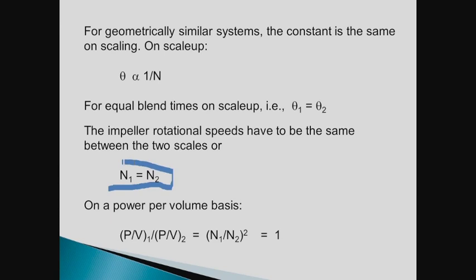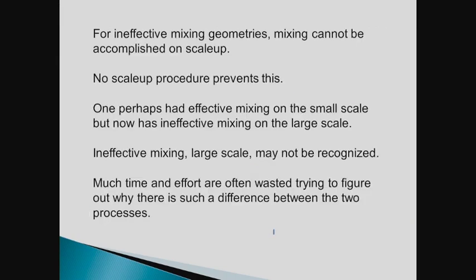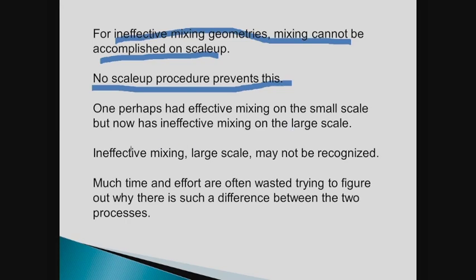Equal blend times. What's amazing about this is it is possible, believe it or not. N1 to N2, equal mixing times were not possible in turbulent flow. Here they seem to be possible in laminar. Kind of interesting. What happens is mixing in laminar flow is stretching interfaces. And to stretch an interface requires energy. And it's saying to stretch an interface, it's the same in laminar as well as turbulent.